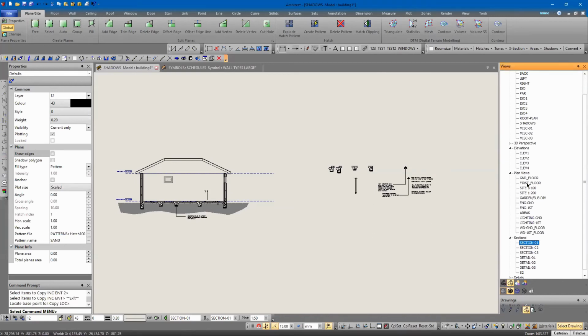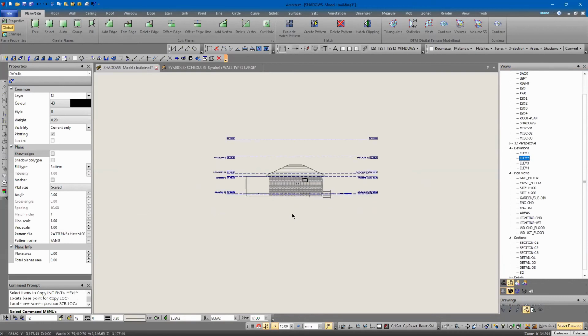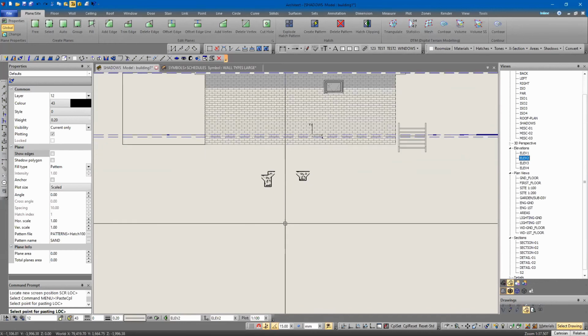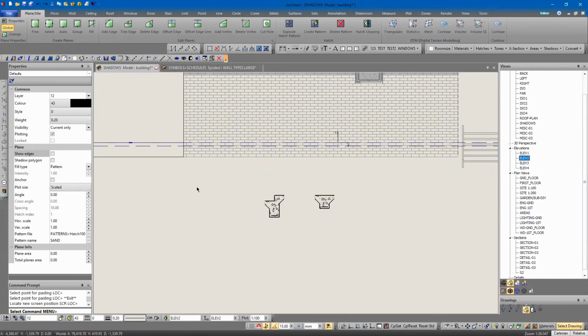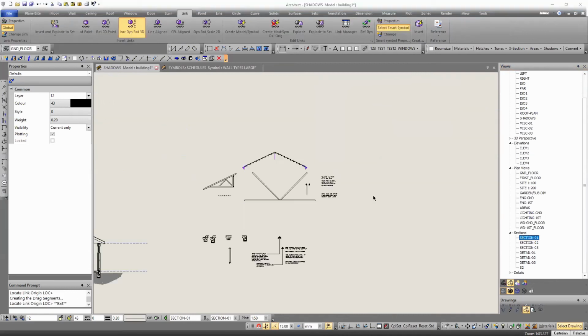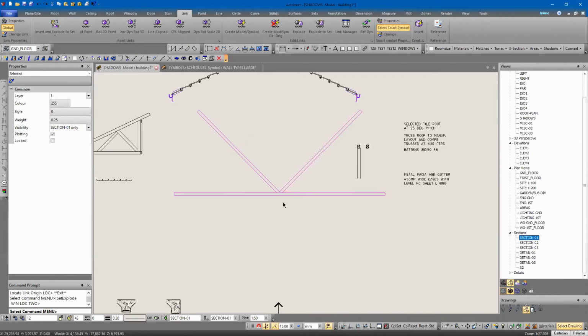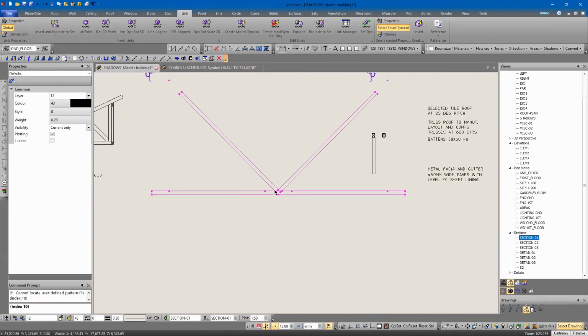And take these items and let's go to elevation 2. I can actually go paste to CPL and I'll paste those flat to the CPL on this view. Yeah. So I can take them from one elevation to another, from section to whatever. So my CPL can be anywhere as long as I'm pasting flat to CPL. Okay, yeah. So these are the different elements that we've got for the roof. This element here is actually solids. So we've got that and that. They're both solids.